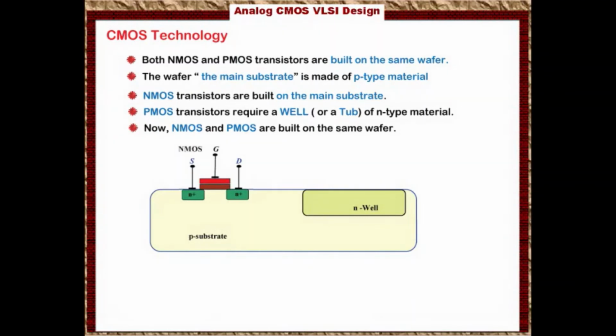The body has a contact with a P+ type material that is connected to the lowest voltage in the circuit, that is usually ground. For some analog circuits that can be negative voltage. So the body of the substrate is connected to the lowest voltage of this integrated circuit.